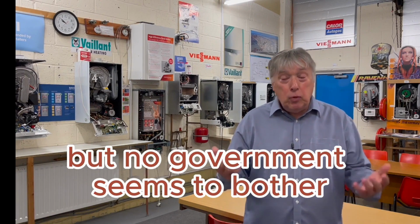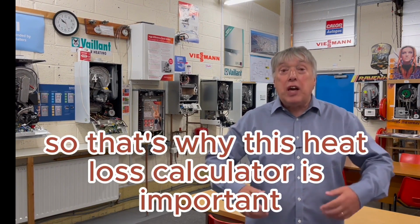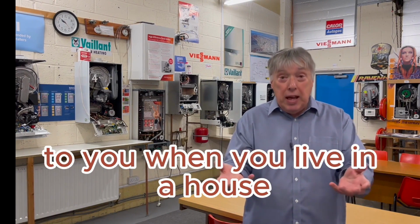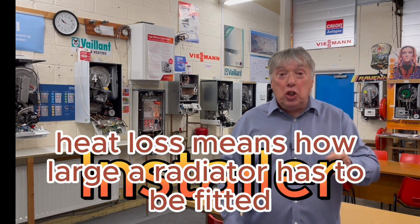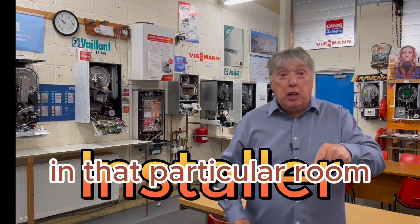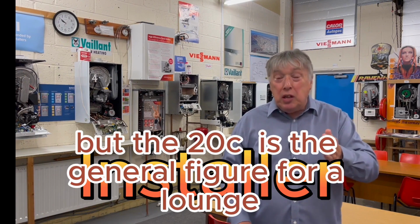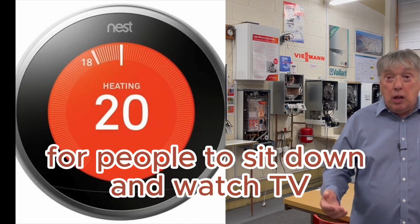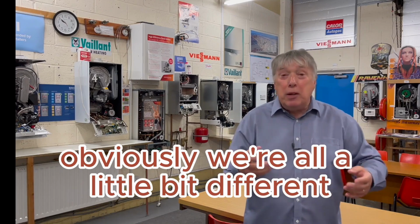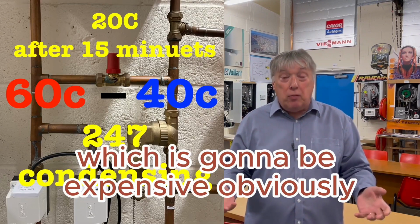It's a shame really, but no government seems to bother about our housing stock and making it as good as those across the channel. So that's why this heat loss calculator is important to you when you live in a house. To an installer, heat loss means how large a radiator has to be fitted in that particular room to take it to a temperature of 20, sometimes 22, but the 20 is the general figure for a lounge for people to sit down and watch TV. Obviously, we're all a little bit different, and some people may say calculate to 22 or even 24 degrees, which is going to be expensive, obviously.